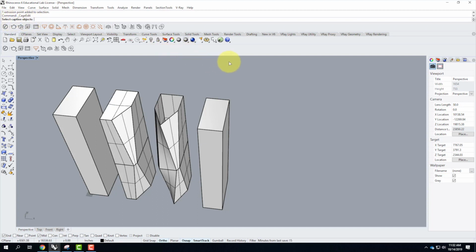So this is the object that's contained inside this edit. In this case, it would be this building. I'll go ahead and press enter when done. Select control object. I'm going to use a bounding box. So around the outside of my building here, I'll click on bounding box. Then the rest of these options are just fine.